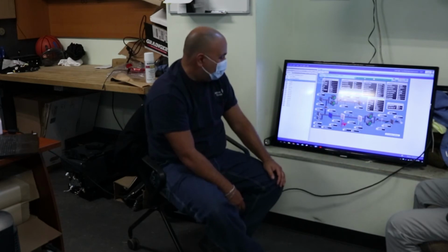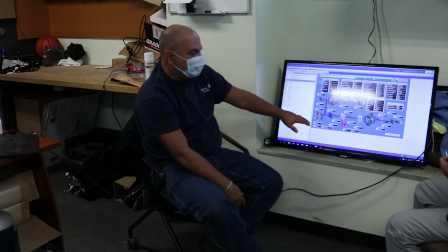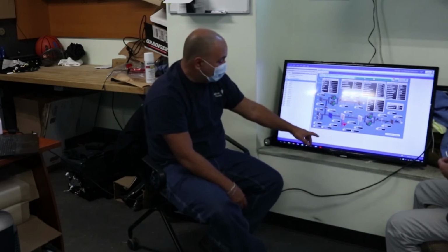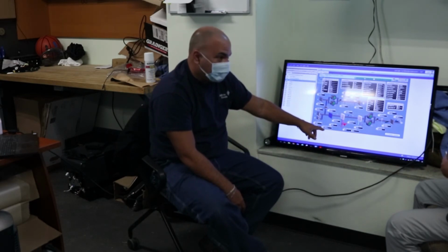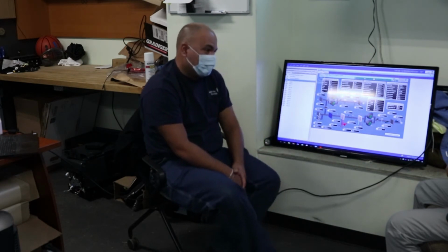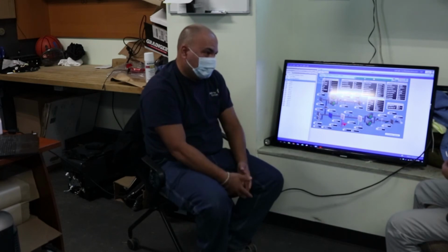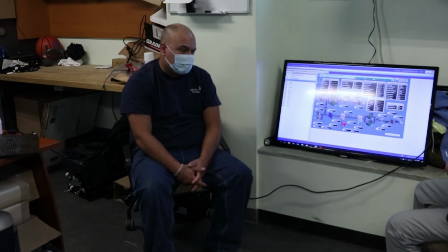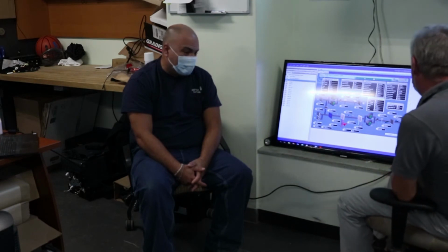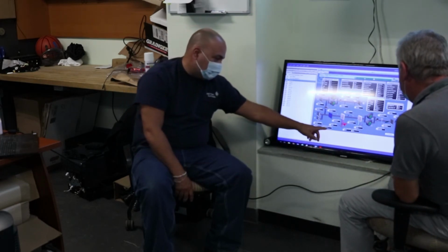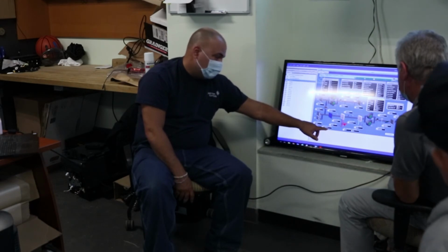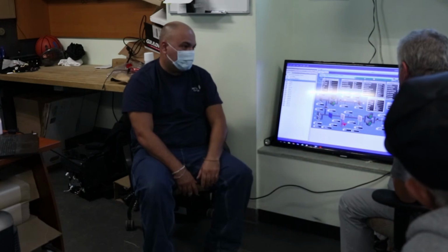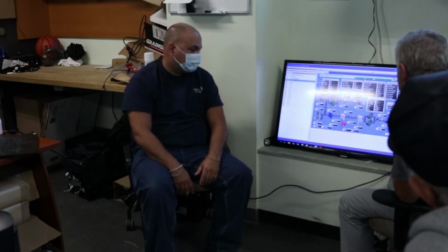But beware, even if the economizer wasn't available, you're still going to be looking to bring in 7,700 CFM of fresh air. It's typically around 60% of the unit that is looking for outside air, which I tend to think will give you some humidity problems in full-blown summer. That's just my opinion. It's a lot of outside air. It's adjustable. It tells you what the default is, so if you guys wanted to change that later on, you can.